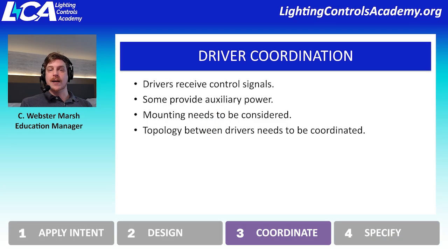If you have an electrical box filled with drivers, but they're all communicating wirelessly, are they close enough to the system to be able to communicate back to that system? Or do you need to add a bridge or a repeater in between where that driver box is going to be and where the rest of the lighting control system is going to be? Those are important things to consider when you're dealing with these drivers.